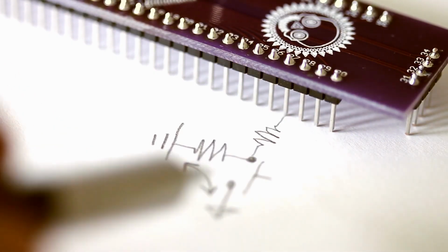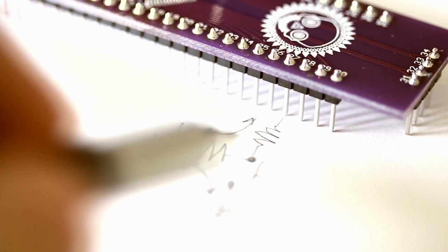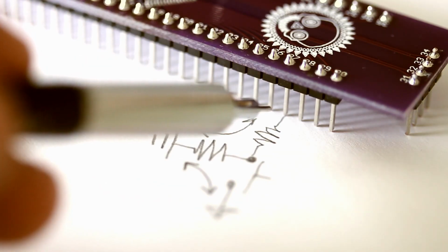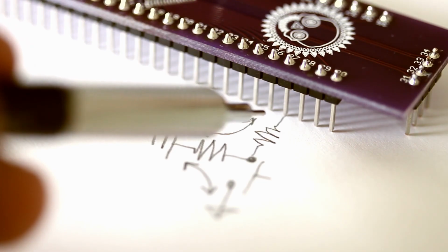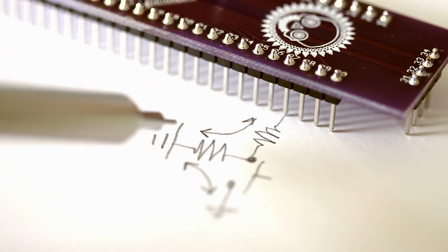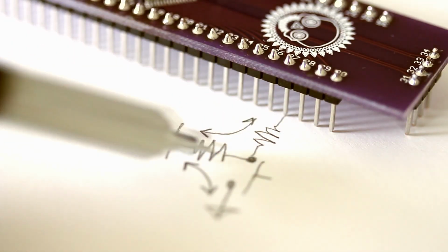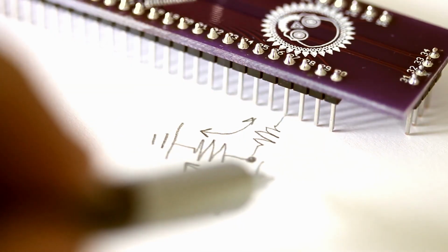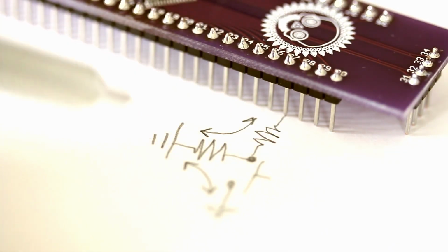When the push button is not being depressed, you'll notice that the pin is going to be directly connected to ground. And what we're doing here is we're pulling this pin down as a natural state. We're doing this instead of actually pulling the pin down internally. We could do that in software where we use the PUPD, pull up, pull down register, and pull this down, but that's only pulling it down to about 40k as specified in the datasheet. And we're pulling it down at 220k, which is a lot more resistance and will draw less current when the push button is pressed.